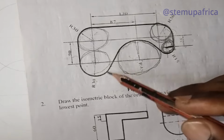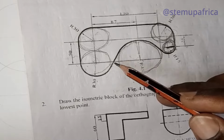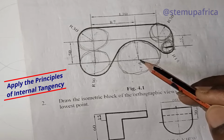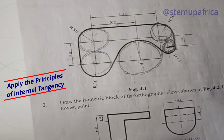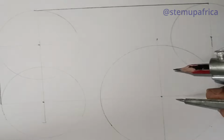You can see there's a line connecting this radius 30 and radius 45. How are both of them connected? They are connected internally. So I will apply the principle of internal tangent. What's that principle? I will add this radius 45 to radius 30. That will give me radius 75. But before then, I need to bisect these two centers, these two circles of 45 and 30.